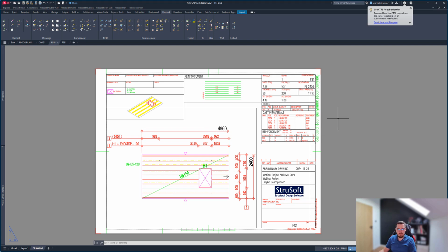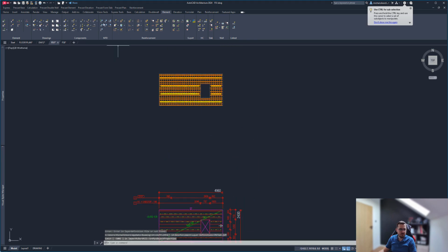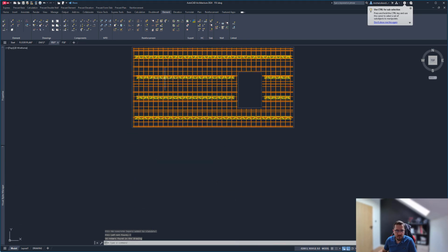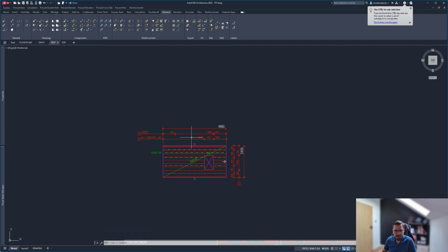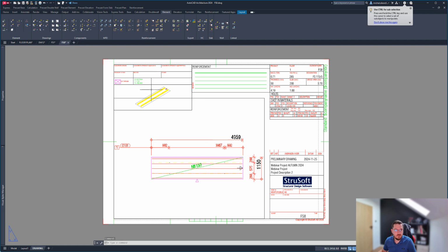Okay, so I think that would be a wrap. So basically, let me go back to the model. Let's draw solid, include reinforcement, include casting material. That should actually include that. Didn't. Yeah. Let's regenerate the drawing. It should actually add that 16 rebar. That's good. Okay. So basically, this is the type of drawings that you get.